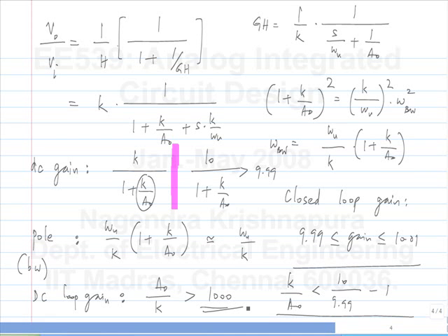So, the accuracy specification has an influence on the DC loop gain. Okay. That's how, when you are making a feedback system, you first of all know that you can't place the pole at the origin, right? It will be somewhere else. And so that means that the DC gain is some finite value. Like how much should it be? 1000 or 10,000 or 1 million? That depends on the accuracy specification. Okay, you don't have to make it arbitrarily large for every case.